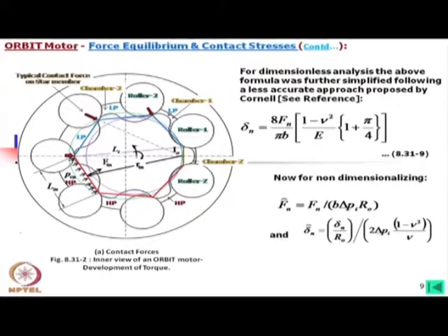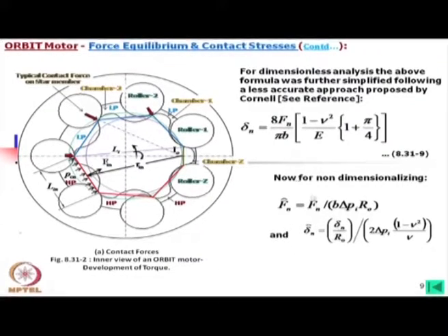The beauty of such non-dimensional analysis is that you can analyze the machine for a particular geometry, and then consider the pressure, actual width, flow rate, everything later to give the physical size of these machines, keeping the geometric relation the same. In the same way we can express the deformations in the non-dimensional form.